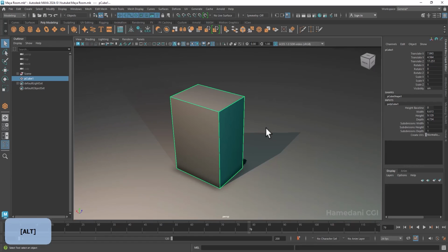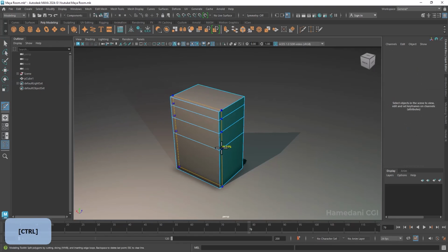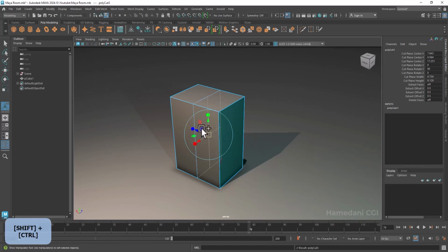I want to talk about multi-cut tools. When you hold Ctrl Shift and X, you have a tool for insert edge with hold Ctrl, or you can add edge free, or you can add vertex and hit enter. And when you hold Shift, you can add vertex in the center. And when you add vertex and hold Ctrl Shift, you have a roller, better connect. And when you hold Ctrl Shift and right click, you have a slice or add edge.